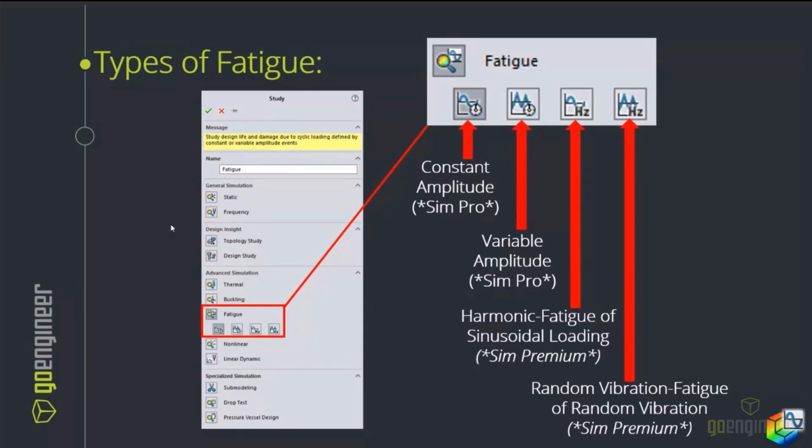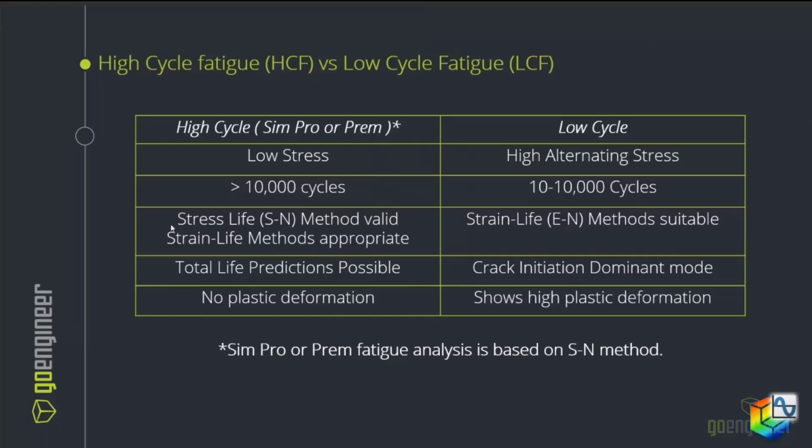Note here, I want to make sure that you understand the type of fatigue analysis method I'm going to be using today for this webinar is the constant amplitude fatigue. Fatigue analysis in SOLIDWORKS Simulation Professional or SOLIDWORKS Simulation Premium is all high cycle fatigue analysis.